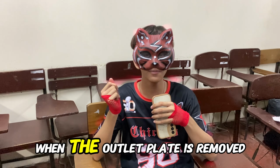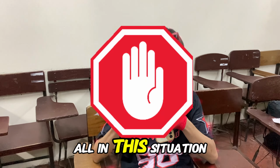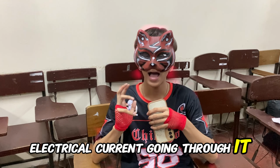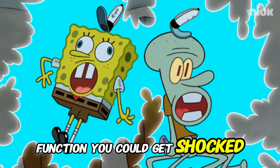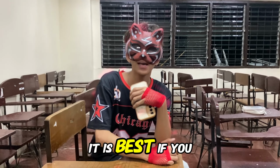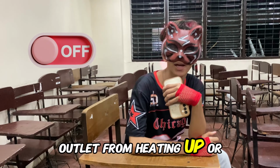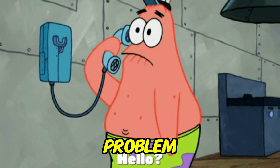When the outlet plate is removed, it is better not to touch the outlet at all in this situation, as there may be an electrical current going through it. As a result of the malfunction, you could get shocked. It is best if you turn off the power at the breaker to stop the outlet from heating up, or contact an electrician to fix this problem.